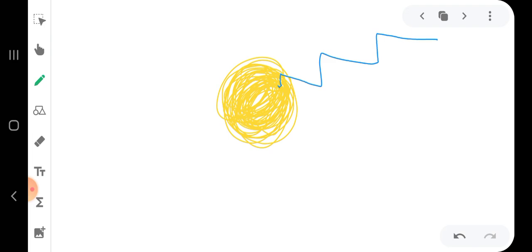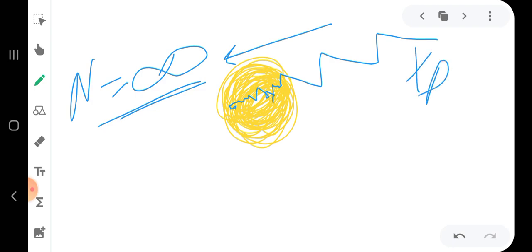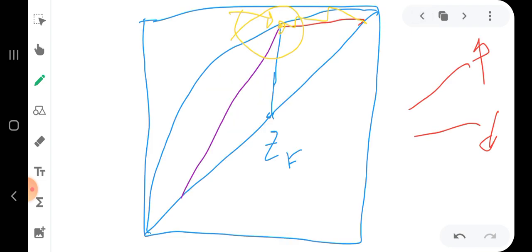Why? Because if you move left, you hit the equilibrium curve at this point, and then you move down, you're still at the point. You cannot move out of this point. In other words, there will be an infinite number of stages, which is not practical. You cannot have an infinite number of stages in your distillation column in order to achieve a specific xD. So that's why we want to avoid this condition. This condition will happen at a value called R minimum.